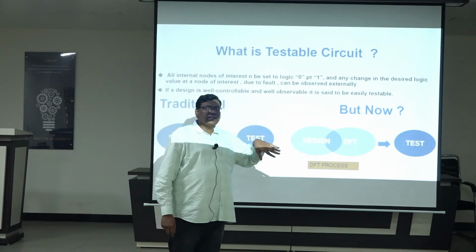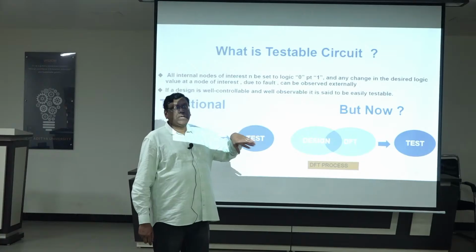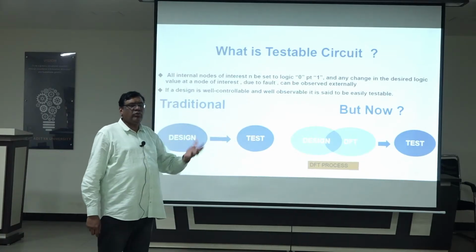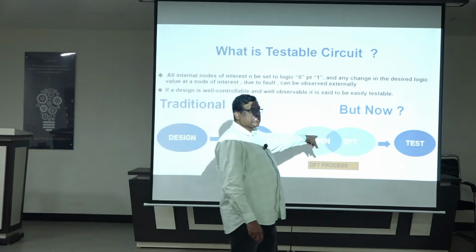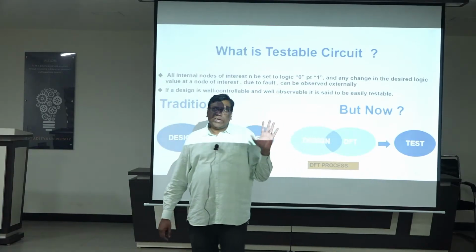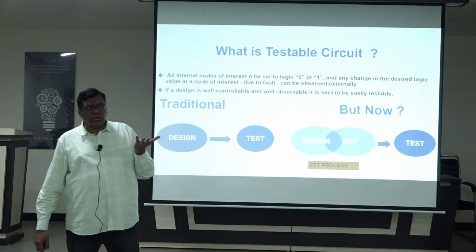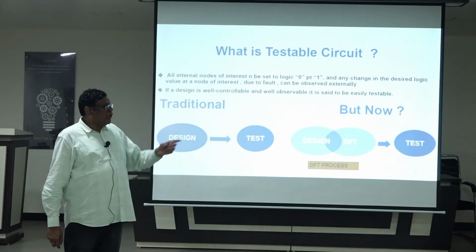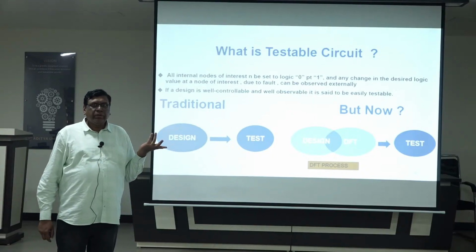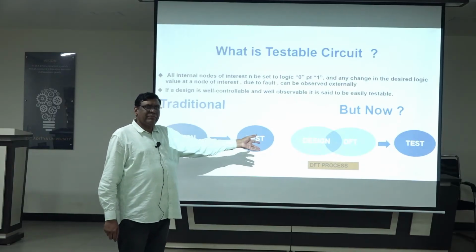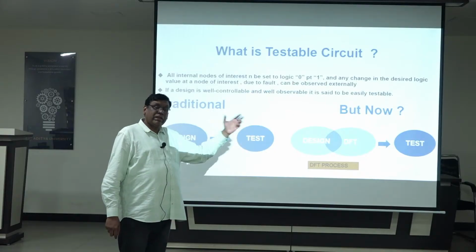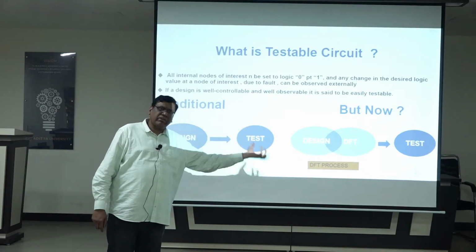Test will be done by another team. But to enable the testing, we will be adding DFT hardware. This DFT hardware, the customer will not use it. So the end user, if you are purchasing an IC, will not use the DFT hardware. You will be using only the design. But we are keeping DFT, almost 30% extra hardware.